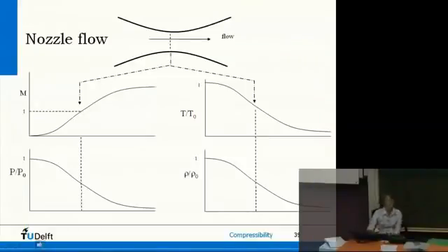So if you make a plot of your nozzle flow, you can plot then for supersonic flow the Mach number. Now with supersonic flow, the Mach number in the reservoir, you start in the reservoir, so 0. Your flow increases isentropically until the throat, and this is then the throat, right? Mach is 1. And then if your area still increases for isentropic flow, your Mach number increases as well.